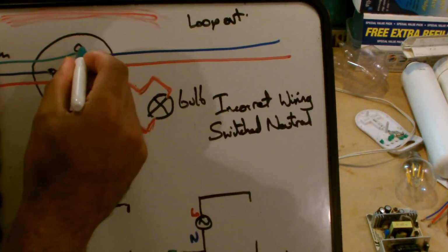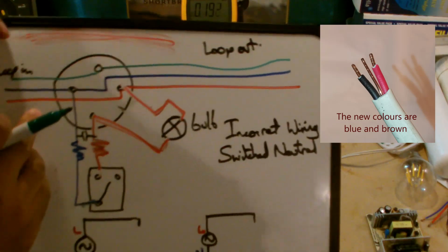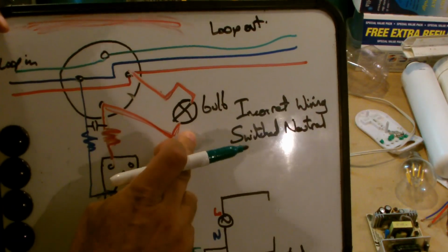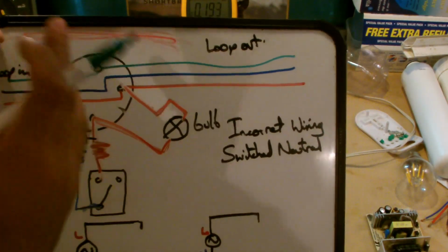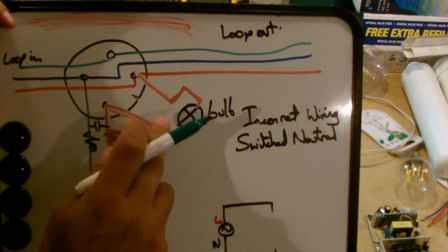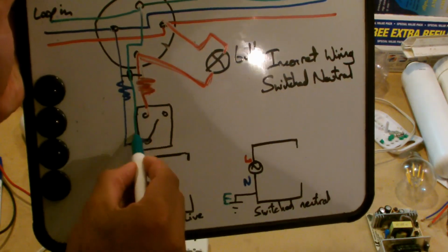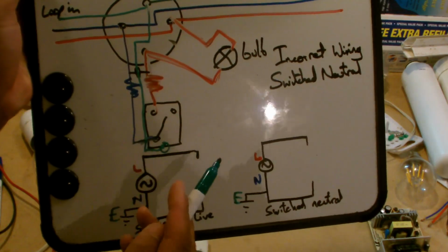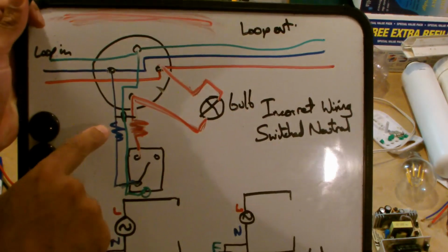So I'll draw this here. That's the ground cable, and we use twin and earth. I think many countries will be using the same thing. As far as the pendant is concerned, a lot of pendants in the UK don't actually have an earth, but if they are metallised they must have an earth. But the earth in this is so short it doesn't really come into effect. Where you have a long line, the earth is part of the effect, and it usually goes to a terminal, which is usually in the switch pattress, but not actually on the switch body itself. We now have this earth in there.